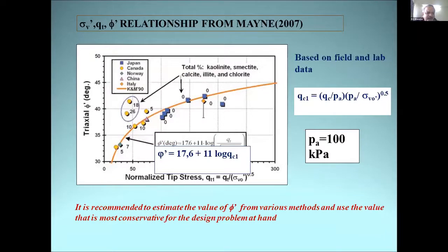So it is recommended to estimate the value of the friction angle from various methods and use the value that is most conservative for the design problem at hand.